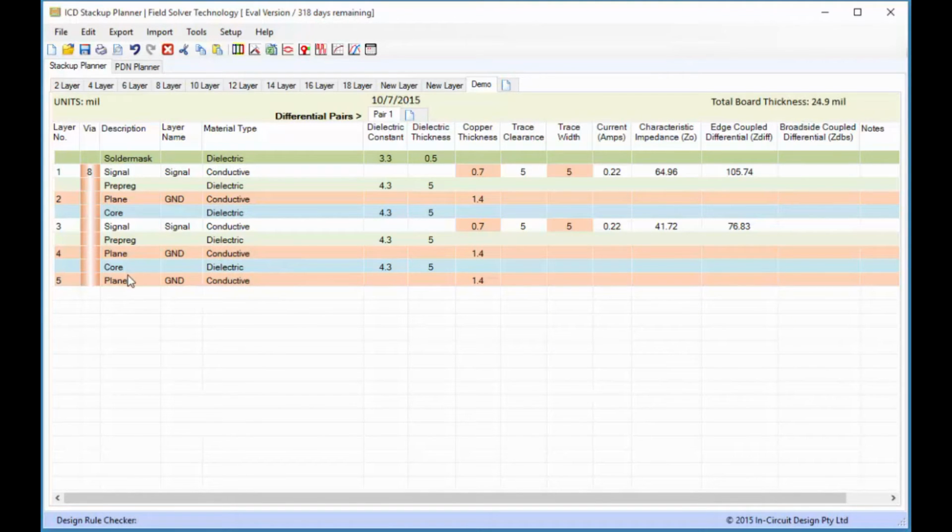All right, and you'll notice, just as a side note, I've got two planes over here. Now why would I have two planes here? And then on the bottom I would have pretty much a duplicate of what I've got on the top. Well, these planes are to make sure that whatever activity is going on at the top doesn't bleed down to the bottom in terms of signal integrity issues, and vice versa. We don't want the noise to cross over so that they impact each other. So that's why we put these two planes over here.